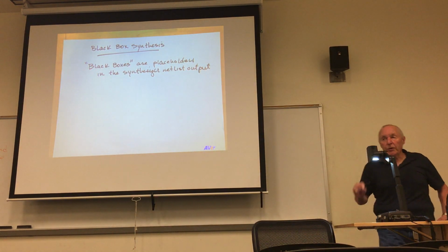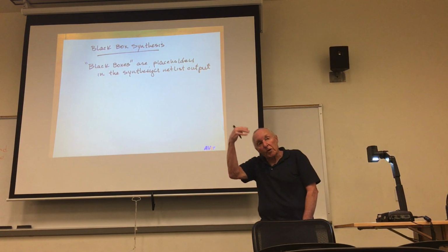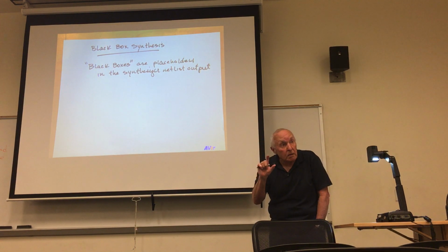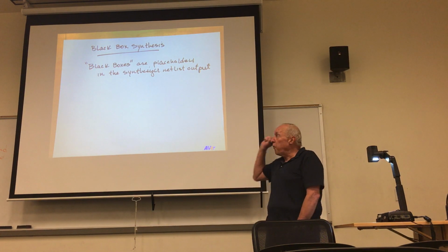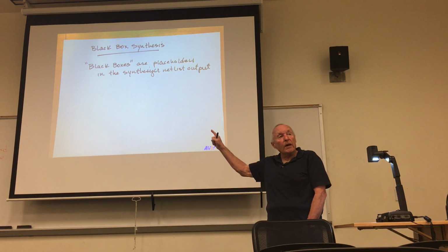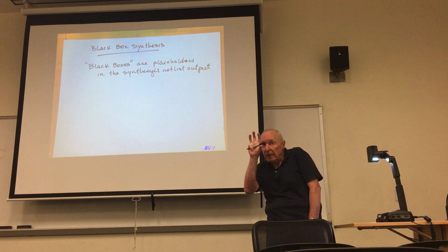Effectively, what I'm going to do is, in my Verilog code, that HDL is going to be an input to the synthesizer, I am going to define a black box. And I'll show you how to do that. A black box for that core that I generated through an IP generation tool. So it's just gonna be a placeholder.